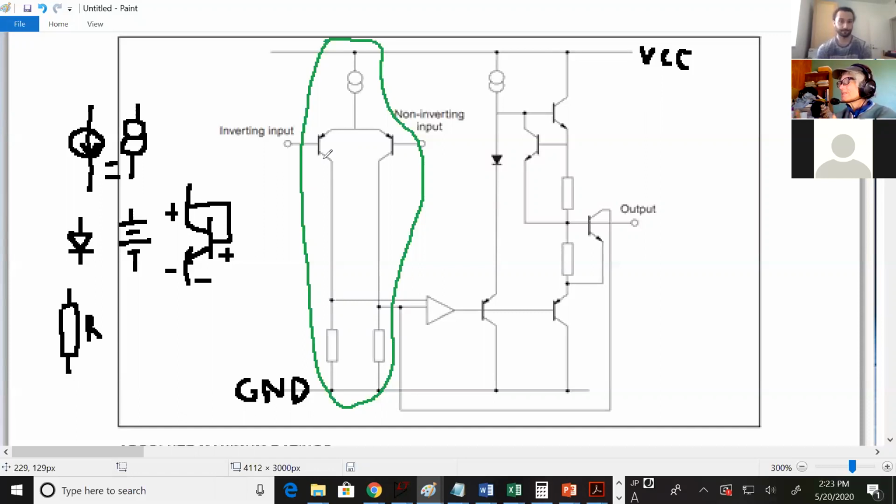So less current would give you the same gain. They're going to conduct less current, but because the resistance looks bigger, they might balance each other out. So I don't have an answer for that. I think it's case by case. You have to go and look at the model file and see what the characteristics of each transistor are. Okay.